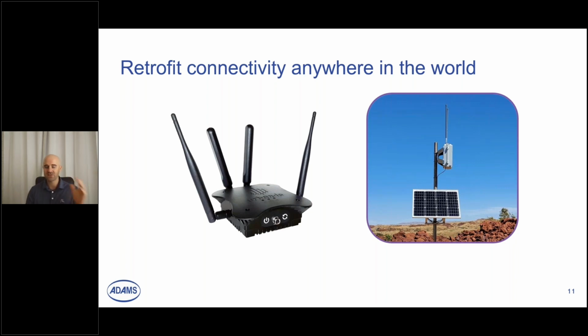On the left side of the screen, we have an indoor rated gateway, so that is IP65. On the right side, if you have outdoor applications, this is more of a solar powered outdoor gateway with an IP69 enclosure and up to 6 days of battery backup. So we'll determine based on our initial site survey, where are you going to mount that gateway?